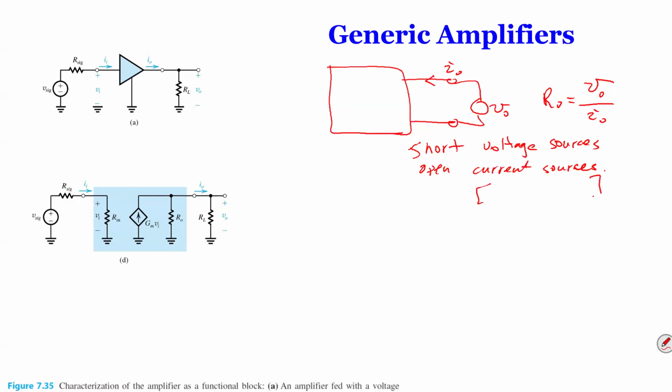Here I want to make a notice: not controlled sources. Because with controlled sources, unless it goes to zero current or zero voltage, you shouldn't open or short it, because you have to leave it there.